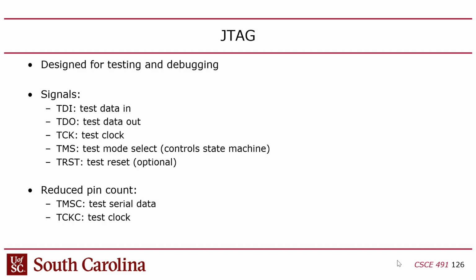Okay, so if you understand SPI and UART and I2C, those are I think a nice base knowledge. You can learn almost any protocol once you know those. There's a few miscellaneous ones I wanted to talk about. There's JTAG. JTAG is used for testing and debugging.